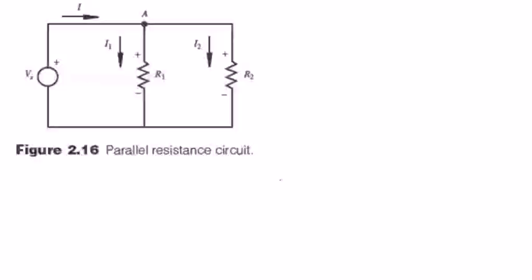In order to do it for this problem, first thing we need to do is for every box in the problem, define a current going through that loop or box. And in this problem you can see there's kind of two boxes, and so for each area we're going to define a new current. For example, we have, let's say, IA in this first box and IB, both going clockwise through each mesh or each box. And then once we define those, now all we have to do is do Kirchhoff's loop law by assuming these currents.